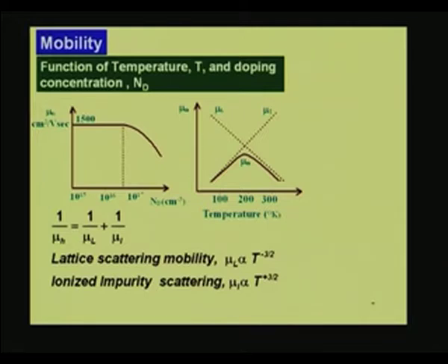So, if you can separate out the ionized impurities and these electrons, then there is no ionized impurity scattering. That means this term is not there. The entire mobility versus temperature curve will be like this. If that is the situation, you go down to lower temperature, mobility can be high. Okay. So, this is one concept, please remember.